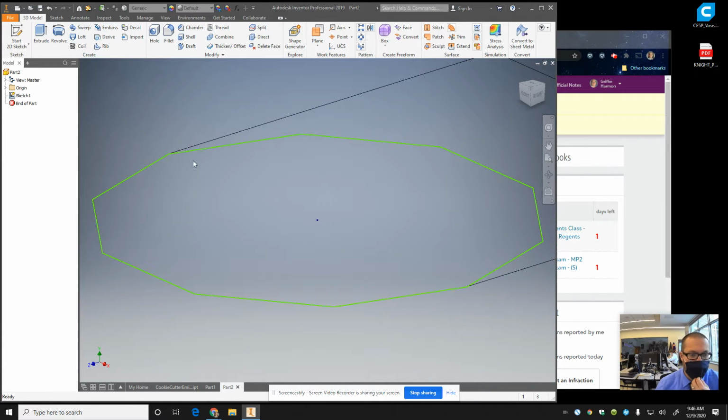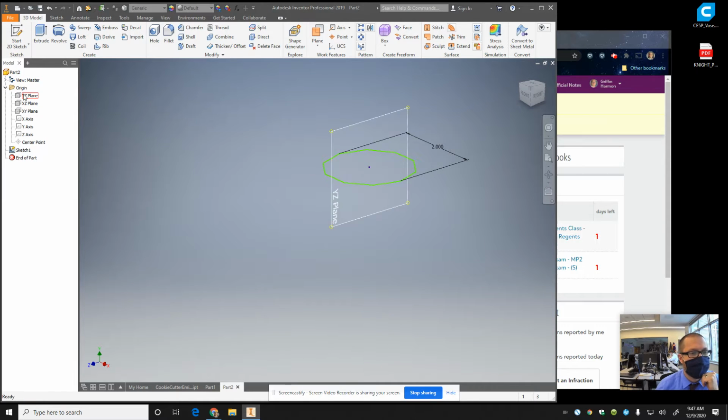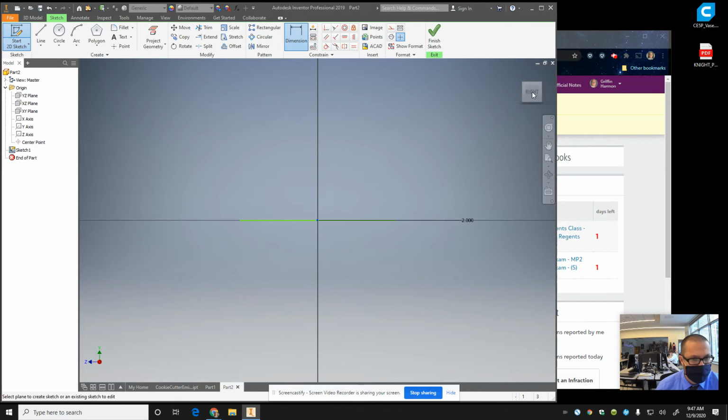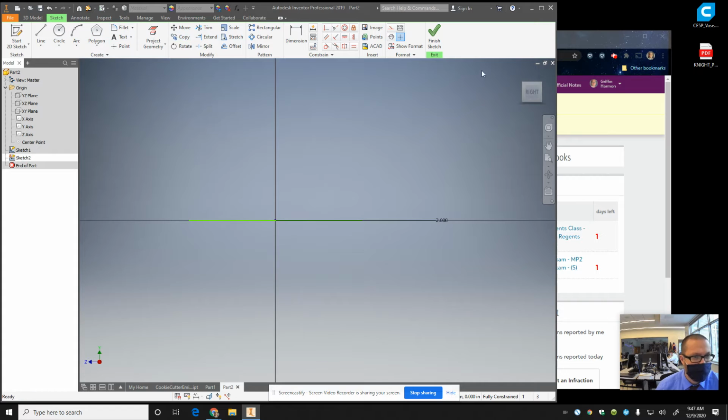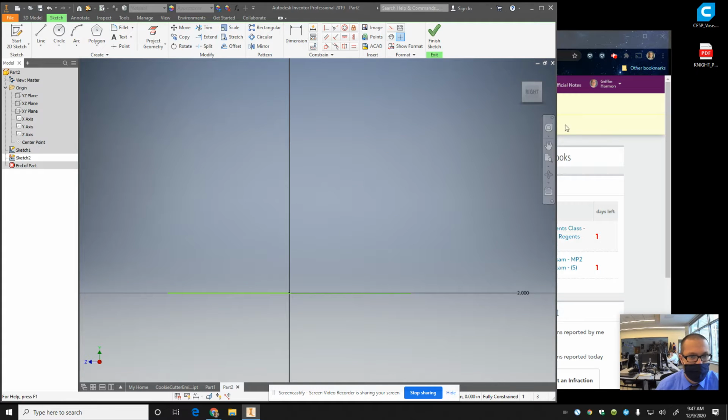All right. So now I'm going to make a work plane through this edge here at an angle to the flat plane. Now I have something in mind here, and I probably should start a sketch on a vertical plane just to give myself a reference. We often use sketches in modeling purely as references, not even part of our model, just as reference lines. So I'm going to start a sketch on this work plane just as a reference as to how big overall I want this thing to be, right?